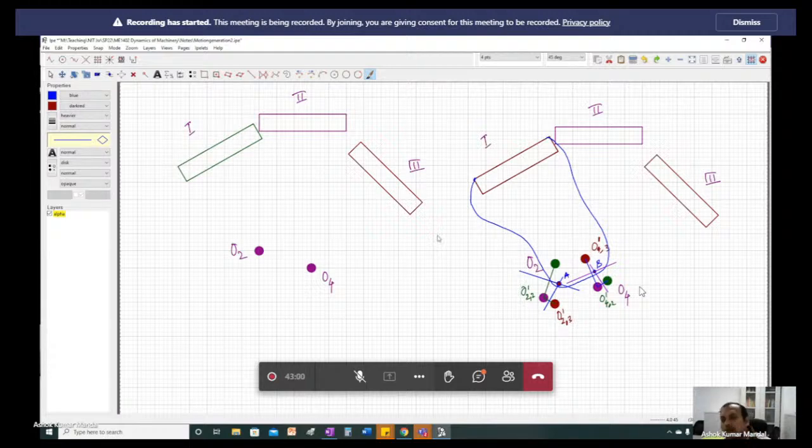Now you can change the problem. The actual problem will be something else, and you will follow the same method to get these points A and B. One can also design it like this: I can have a shape like this, where this portion has no material, but the whole thing is a rigid body, and on that rigid body you have two hinges A and B. These two hinges A and B, and the original points O2 and O4, give the four-bar mechanism which ensures positions 1, 2, 3 when it is rotating.